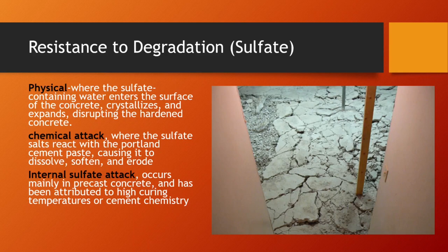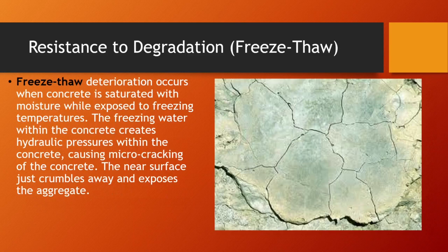Certainly we get certain additives, pulverized ash, for instance, aluminates, sulfates, all sorts of chemicals, retardants, plasticizers, all different chemicals to make the concrete react in different ways to certain situations. Now, freeze thaw is the main problem, and effectively what that is, you can see the image on the right.